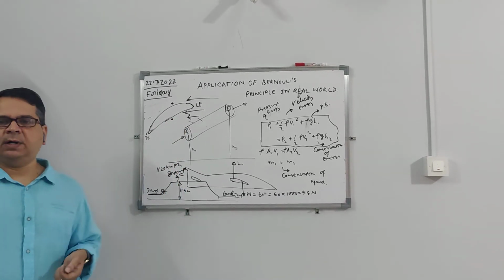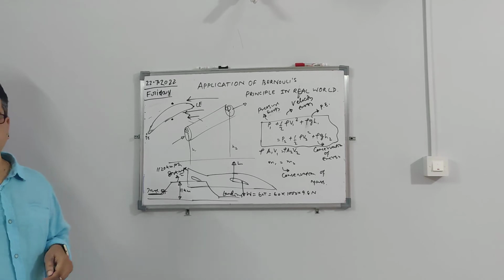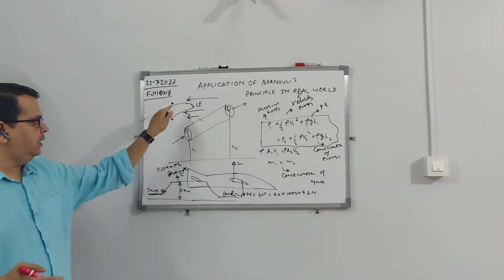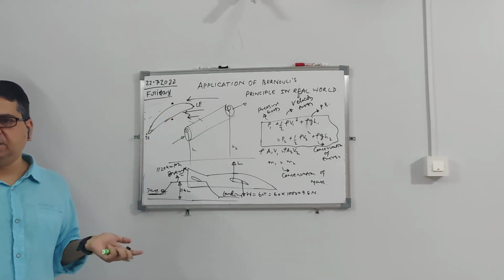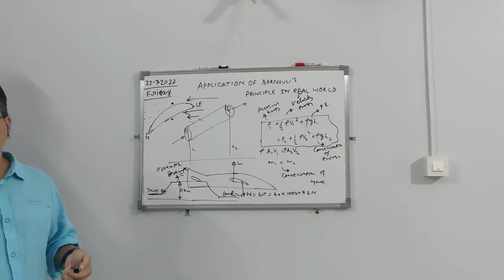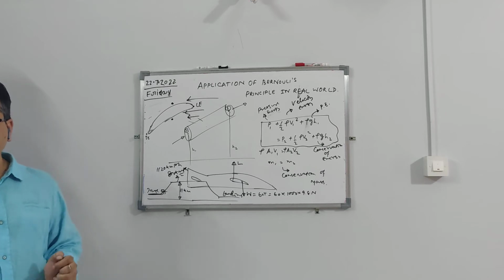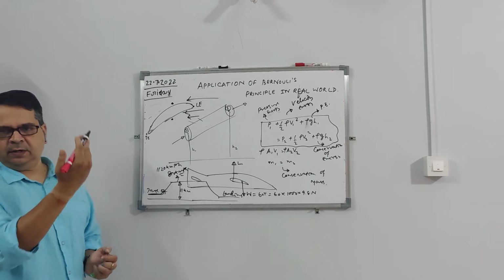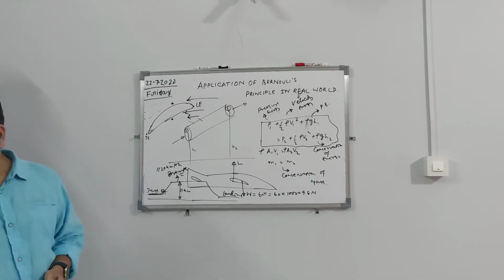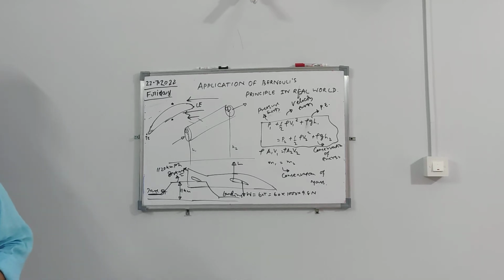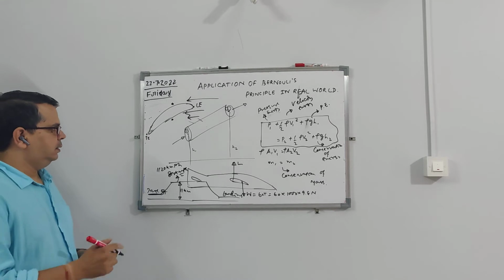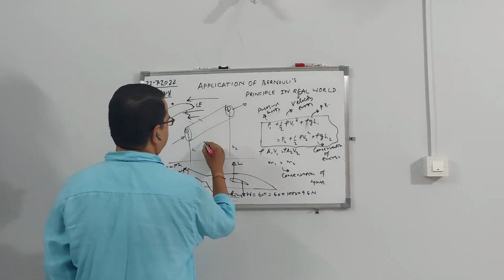Pressure into area is nothing but force. So there is a lesser force acting on the upper surface and a higher force acting on the lower surface. This difference between the upper and lower pressure force will try to lift it up. It is something like this.